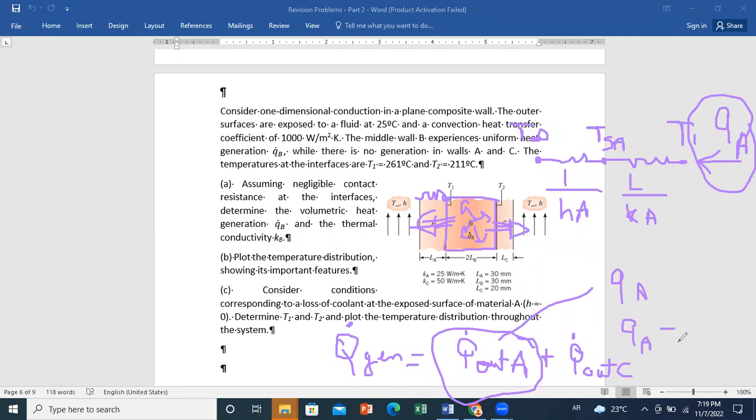And it can be calculated through the thermal resistance concept, because I can write that QA is equal to delta T between T1 and T infinity over the sum of resistances. So I can get Q dot out through A. You have several symbols you use. Maybe you are familiar with Q dot, or you are just calling it Q if it's the total rate in watt, and per unit area you call it Q second. It doesn't matter the names. What matters is that you know how to treat the problem.